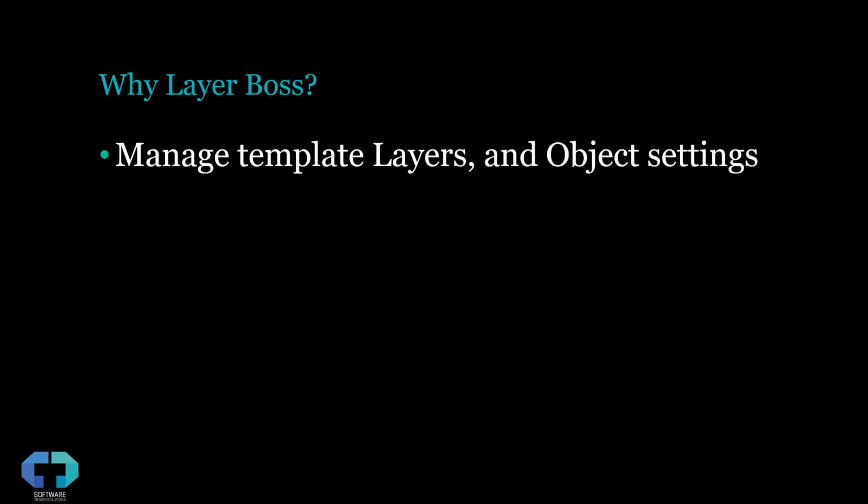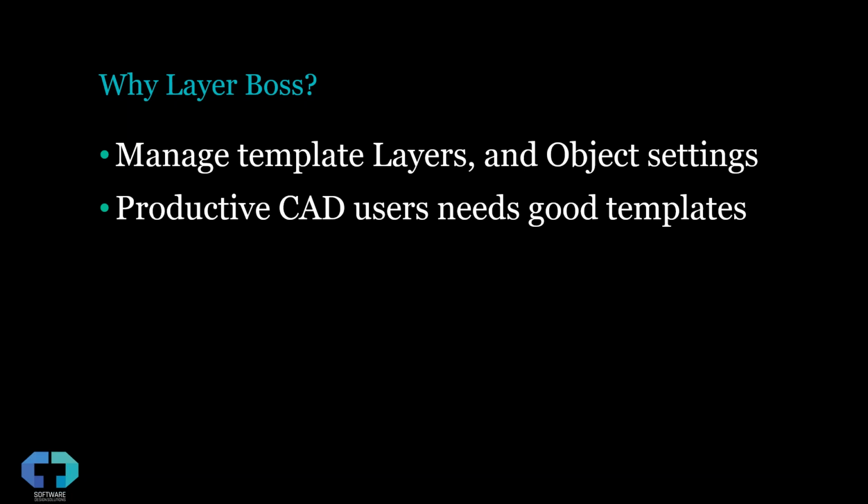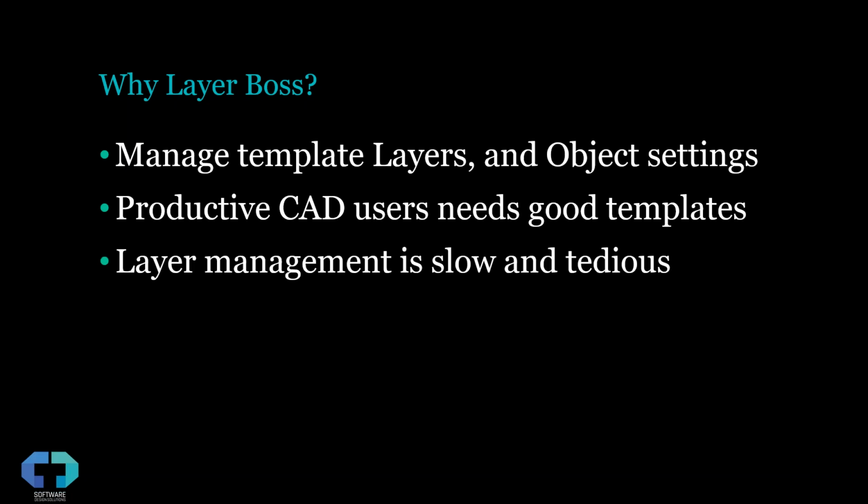So what is Layer Boss? Why do we care? First off, it's about managing your standard layers as well as your Civil 3D object layer settings. It's giving us a quicker way to do this. And if we step back and think about it, what makes for good productive CAD users? One is they need to understand how to use the tools, but they of course need good templates. And so creating and maintaining and editing those templates are quite important.